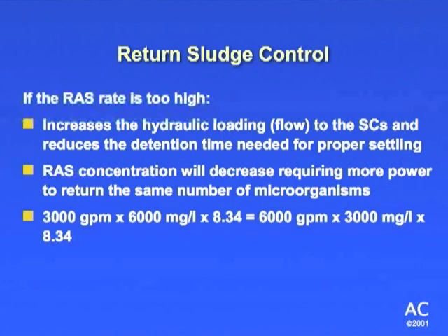So when you're returning like that, a lot of times when you're returning too fast, what happens? What do they call the situation if you're returning too fast with a sludge? Coning, or have you ever heard that? Rat holing, coning. What happens is you're now pulling water with your sludge, and you're diluting your sludge. So you need to just back off.